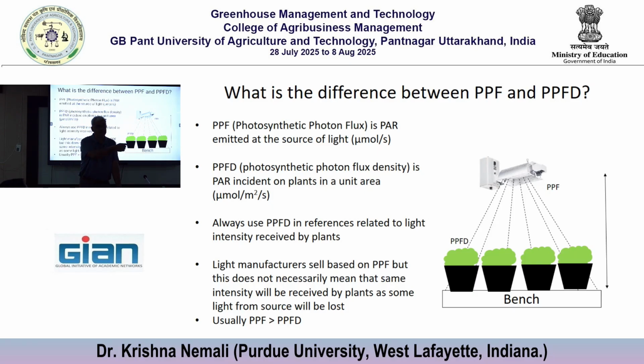You may get a little benefit for the temperature, so that's actually added to the benefit side, not the disadvantage side. But you won't get the favorable light bands we require, composition wise. Still, because the cost is less, high pressure sodium lamps kind of dominate the industry. People are worried about investment because LED investment is big. Like I said, you have to wait for 10 years to start seeing the benefits of lower electrical energy costs. So investment can be big for some people, and they still want to invest in high pressure sodium lamps.